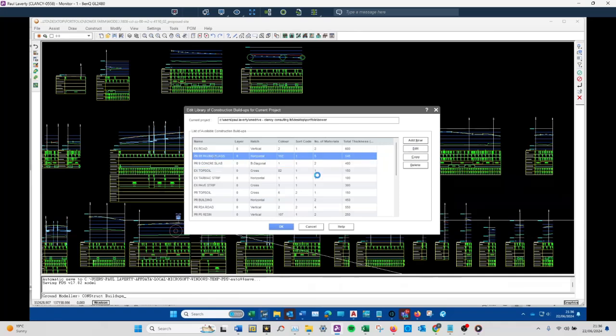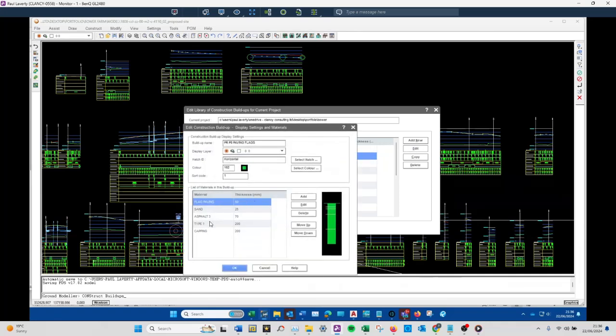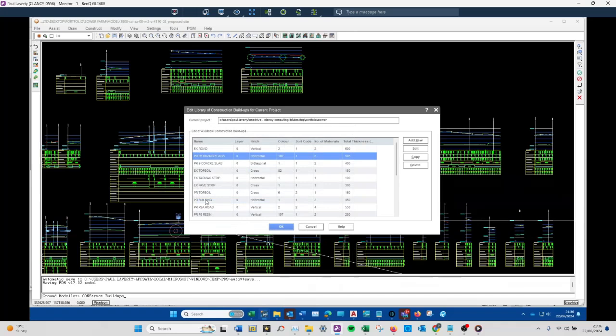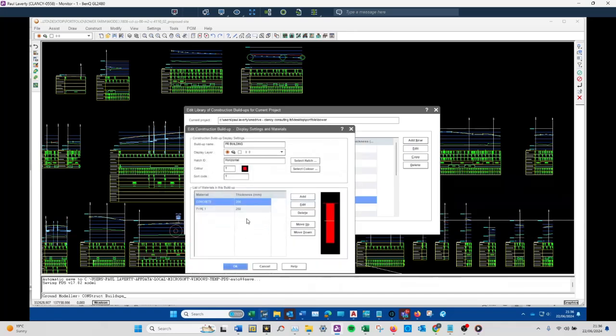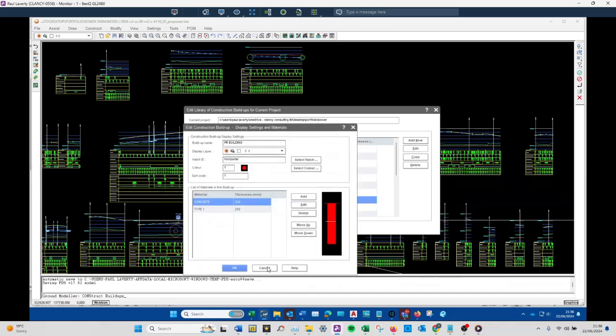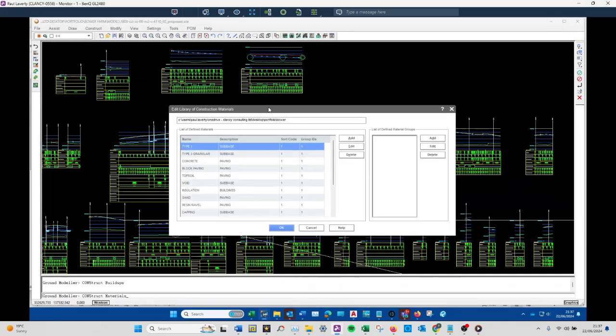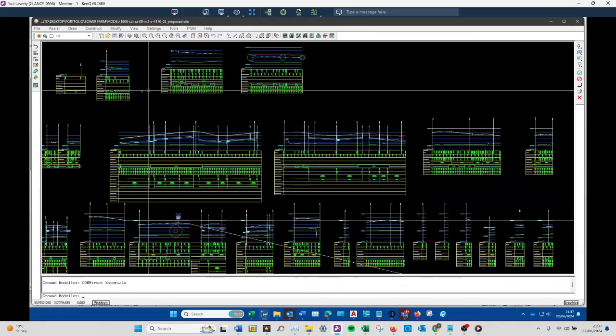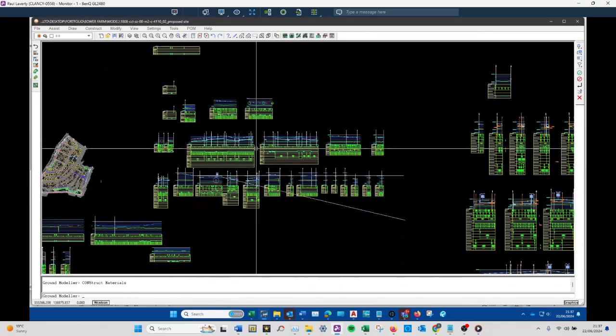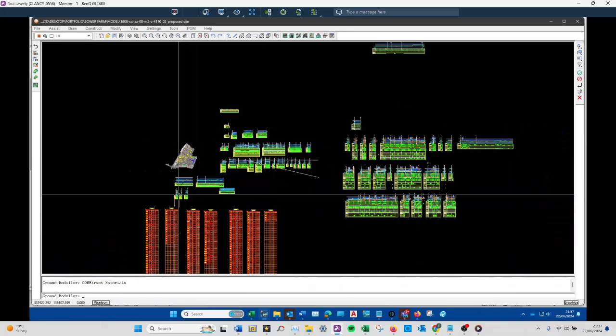So you'd use your block paving, your sand, your voided subbase, and a bit of capping, 6F2, whatever. Those will all be in groups, and you assign the depths to them so that when you compare your ground level DGM and your formation level DGM, you can get the volumes of all the different materials, and it helps with getting the volumes of your cut and fill exercise. Again, I'll go into this when we go into your build up videos and your kind of fill build up videos.